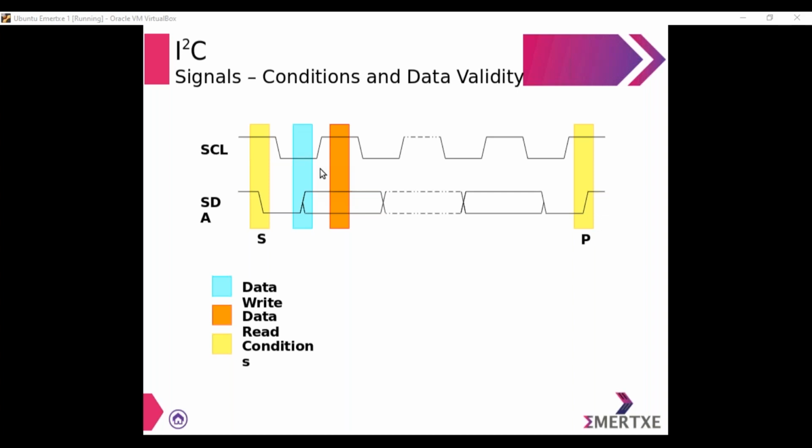If D1 out is equal to 1, then the remaining are going to get 0. That means communication only with that slave and the remaining slaves are off, in the wired AND. So if D1 out is going to receive a 1, that represents the data line. With D1 out, you are not getting a 1, you are writing a 1. Then all other devices in the network are going to get a 0 from the data line. That represents the line being busy and somebody is using that data line.